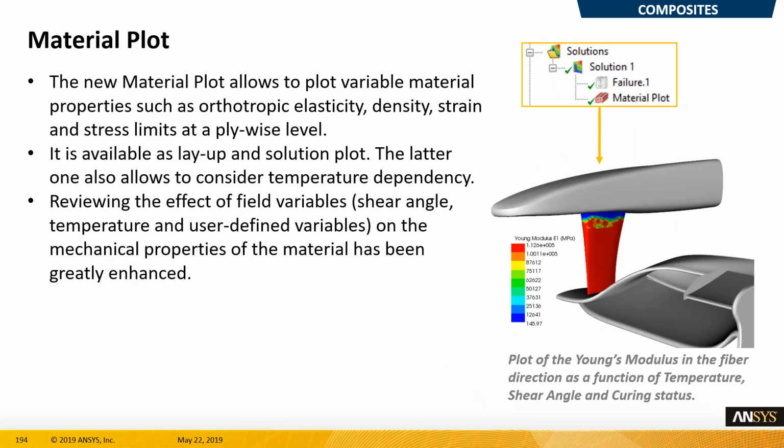Material plot is also available now, so you can actually plot the thickness or the Young modulus of the different directions directly within the ACP environment. It's quite useful sometimes to see how the E1 or E2 or the G11 or G12 is actually on display here. That could sort some of the layer faults we see often, where you miss a selection of your body.